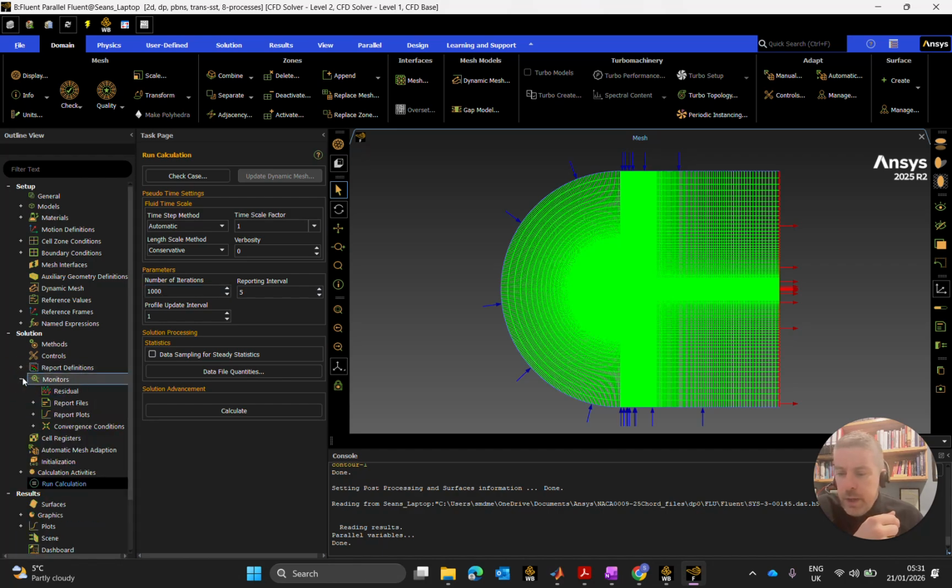What I'm going to do, and also the lift coefficient and the pressure coefficient also have to converge. So I have a problem because my lift coefficient and pressure coefficient at angle of attack of 5 have obviously converged. So the value that ANSYS has found thinks that, yeah, you've converged. So there could be a problem with how I'm converging.